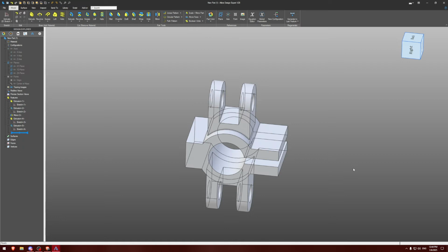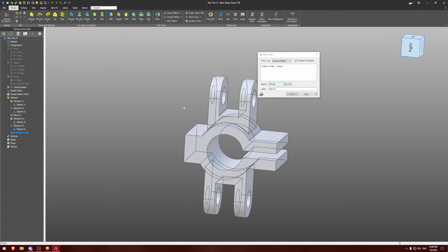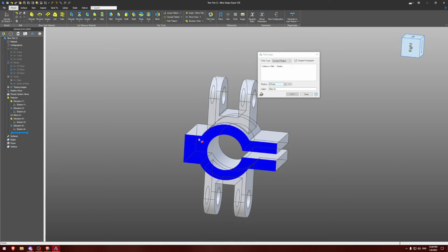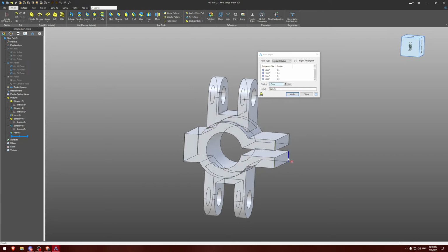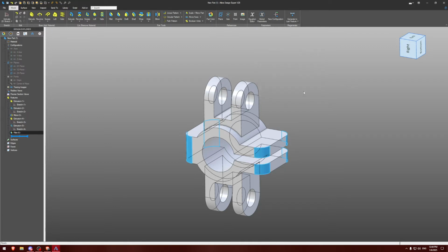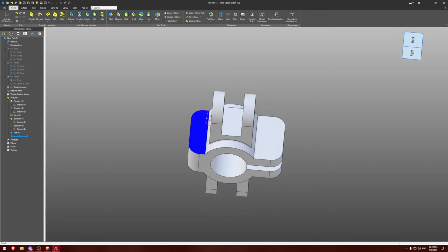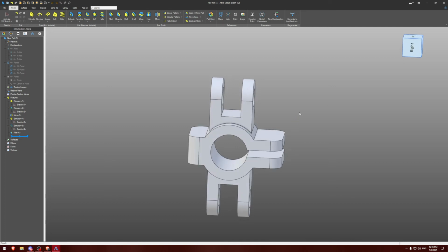Let's go ahead and do our fillets here. Let's add our 16 fillets. That's there, there, there. All right. And then we need the slot and the holes as well as the triangular part. Ooh, while I'm here, what's the other fillet? Our 8.